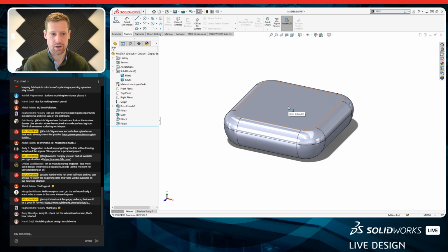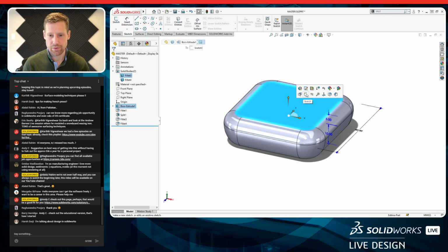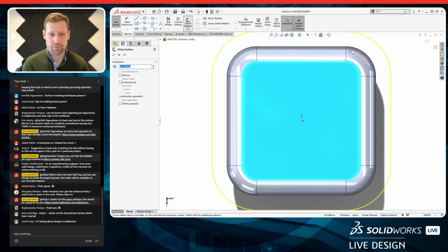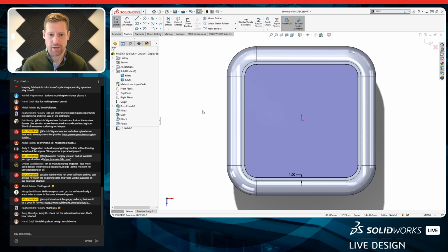Here's another tip that I like to use a lot. I'll select this top face, and I'm going to choose to sketch on that face. Now notice that the face is still in blue. It means it's still selected. So that means I can perform operations with it. So if I want to offset the edges of that face, I can just simply come to Offset Entities. Okay, now I can choose how much I want to offset it by, maybe 1 millimeter. I'm going to set it to the inside, and then confirm that.